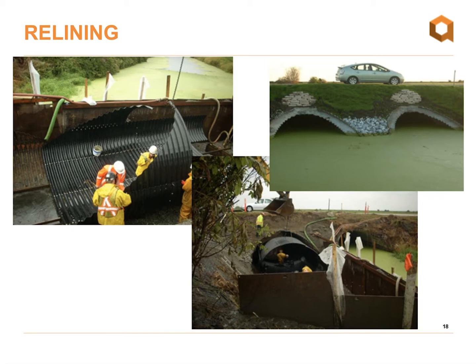All right, so relining is, again, as I said, really the focus of the presentation today. Just to talk a little bit about why reline can often be a great solution for rehabilitation. Oftentimes we're dealing with structures, as you can see in the top right photo there, where a galvanized steel system was put in place, and it really shouldn't have been. Back in the day, we didn't have as great an understanding of the chemistry of the interaction between the steel and the aqueous environment in which it's installed.